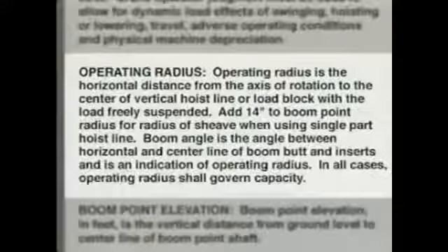This part of the capacity chart provides information about the maximum boom and jib lengths that can be lifted unassisted. These 3 blocks provide that information based on different crane positions and boom lengths. Never attempt to raise a boom or a jib that's longer than what's allowed under the conditions specified on the chart.